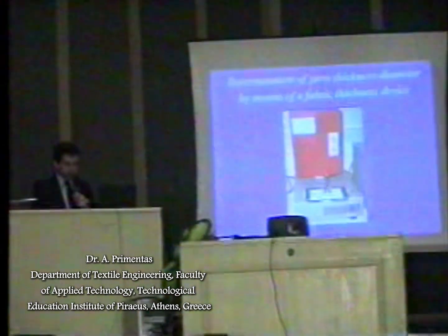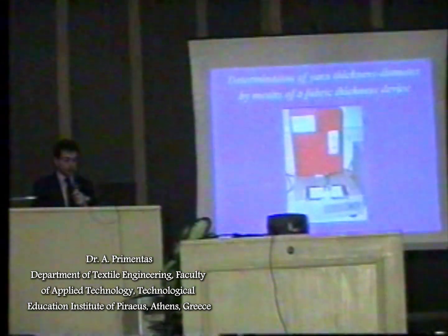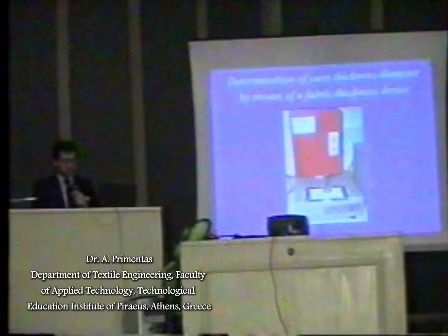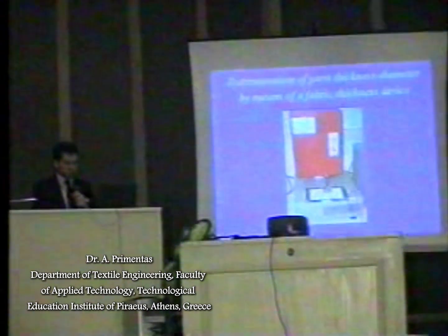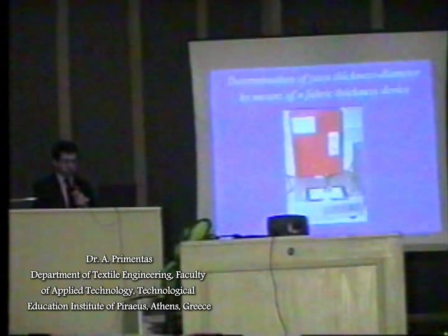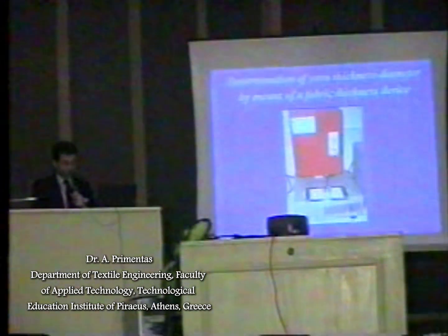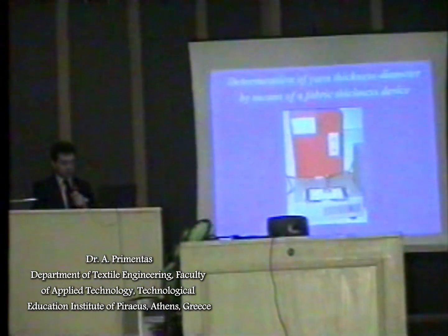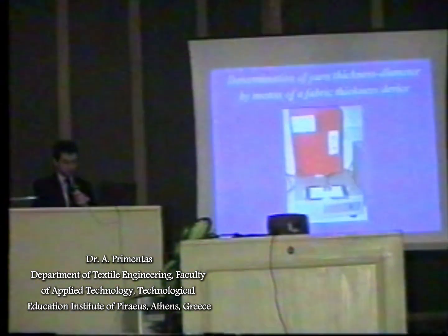In this case, yarn thickness diameter was considered the distance between the reference surface, where the yarns were laid, and the pressure foot that set a load on them. The frame thickness was such as to avoid any yarn disturbance in terms of horizontally formed angle, always lying on the reference surface. Moreover, the movement of the frame on the reference surface was made with much care as before.